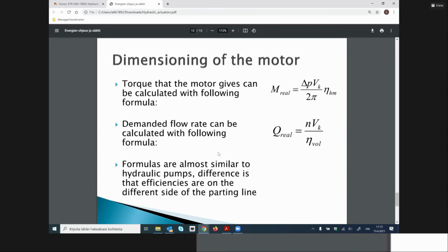Then I think it's simple. There was not enough power from the combustion engine to spin the pump, and maybe the pump was already a little bit old, so there were some leakages in the pump, and you needed to rotate it at higher speed so that you can overcome all the leakages, and only then it would be able to generate the needed pressure and needed flow for the cylinders.